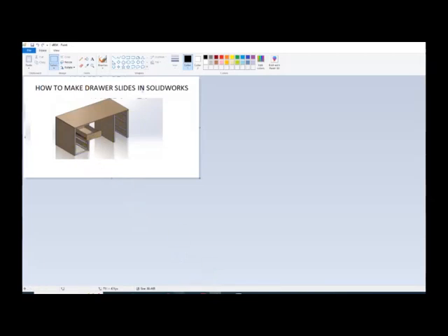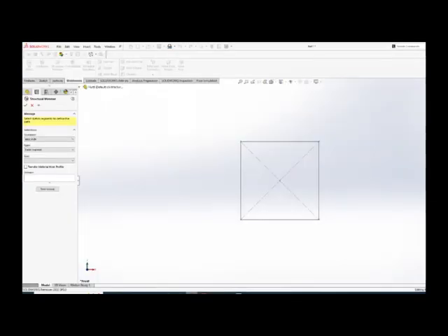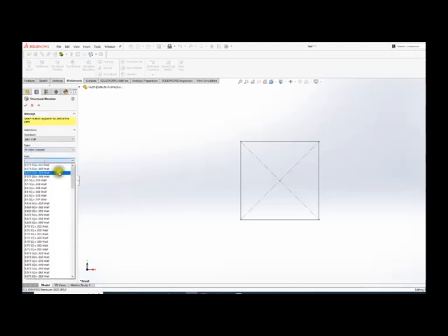So I have a problem. Going back to SolidWorks here, I have to get those because it's not here. You see, that's the problem. I'm in ANSI inch square tube, but it's not there. Maybe you can use aluminum tube square, size 1x1 square with a wall of about 0.065.